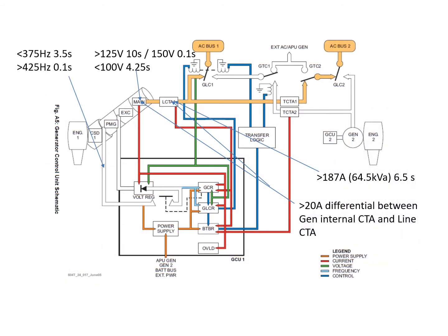Okay, so this picture, if you remember back at the table we looked at a little earlier, where we had all the limitations, so the over frequency, under frequency, over and under voltage, and so on. Well, this picture is just showing you where that information is coming from. It's all being processed by the GCUs, but this is where the GCU is measuring this information from, like the voltage and the frequency and so on. So I'll just leave that on for a couple of seconds just for you to peruse it.